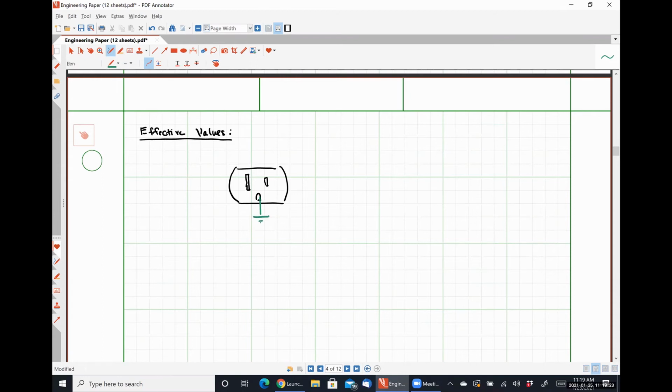This guy down here usually has a green wire connected to it, and it's going to earth ground. This guy right here usually has a gray wire, and it is going to the neutral. And this guy right here actually usually has a white wire, but I can't draw a white line. And this is what would be called our hot wire.